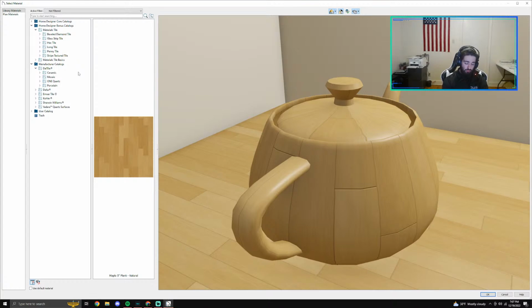So we're gonna use Guru for this case. We're gonna use Go Board for the walls and Multimax Light for everything, except for the main floor tile. Everything that's in the shower is going to be Multimax Light. Everything that's in the main area is going to be 254 Platinum. So we're using all the good material, and I'm pretty much supplying everything except the tile.